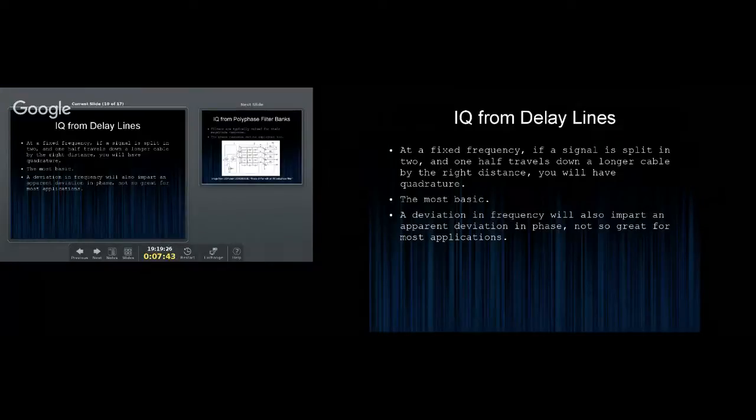So you've probably seen something like this before, maybe in using dipoles to obtain circular polarization. They've got different length cables. And anyway, it's not really that interesting, apart from perhaps in radar systems where they want to align the phase wavefronts. So you've got switchable banks where you can change the physical length of the path so that the phase arrives at the correct angle.